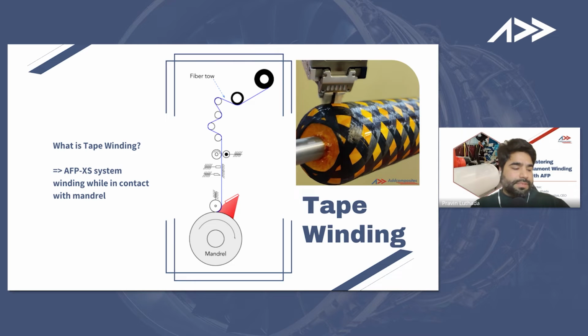What this enables, compared to filament winding, which is limited to either dry or wet winding or prepregs, is that with tape winding you're able to make thermoplastic wound shapes, which is where we would want the composites industry to go because of the sustainable and recyclable nature of thermoplastic composites.